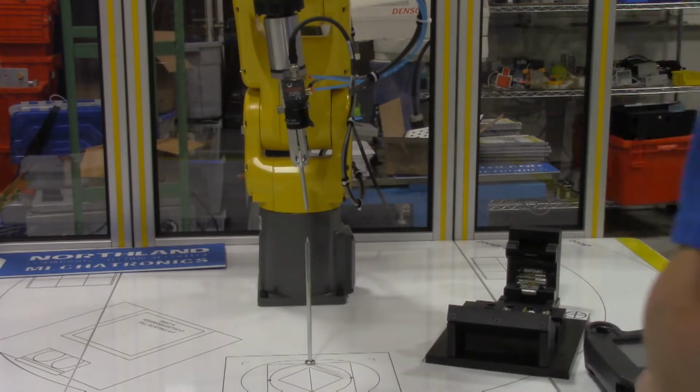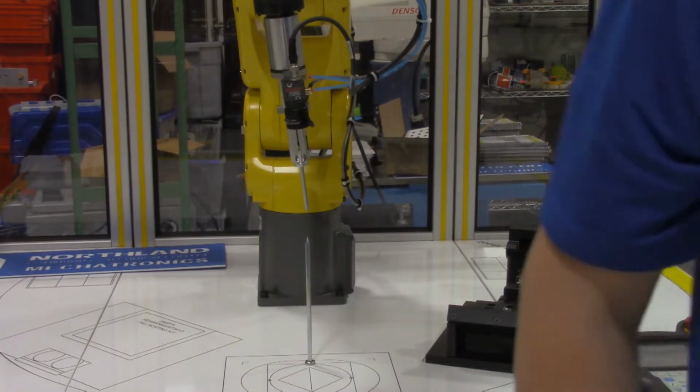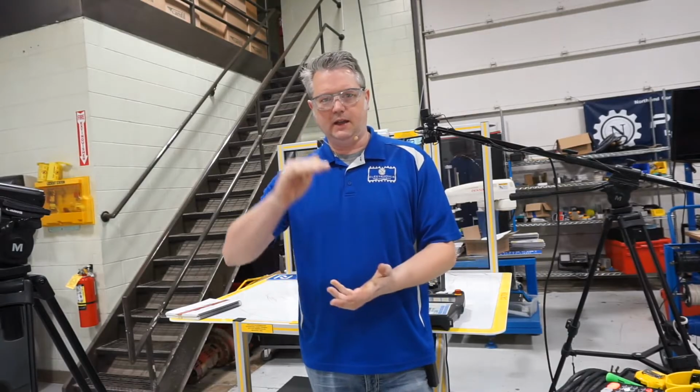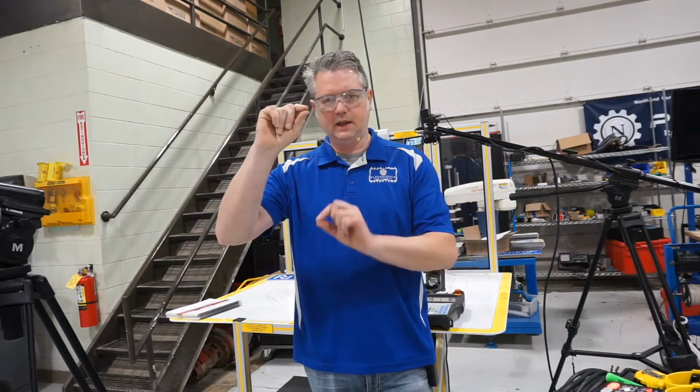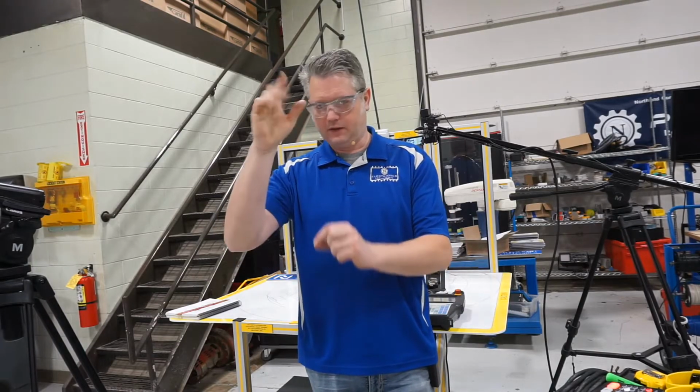All right. So that's one method of entering a tool frame, which is to do it through direct entry. If you can take the measurements, if it's a simple offset from the end of the tool plate to the tip of your new tool, if it's straight Z, you can just enter that height. By far the simplest method. If you have a CAD model, you know the exact dimensions.